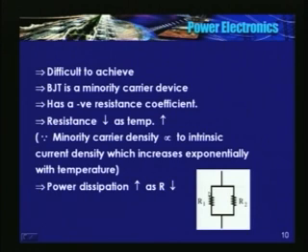As the current in R1 increases, power dissipated in R1 increases, and so temperature increases. Now if temperature increases, again there is a reduction in the resistance because it has a negative resistance coefficient.